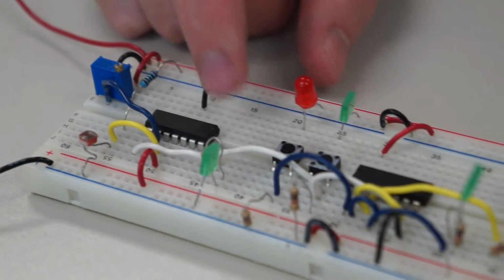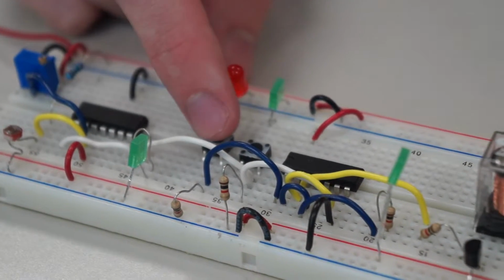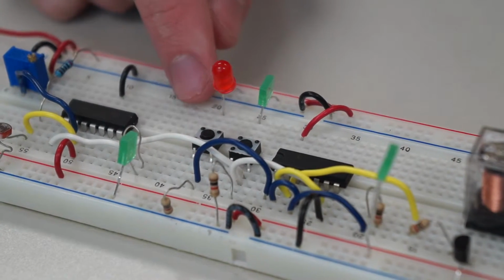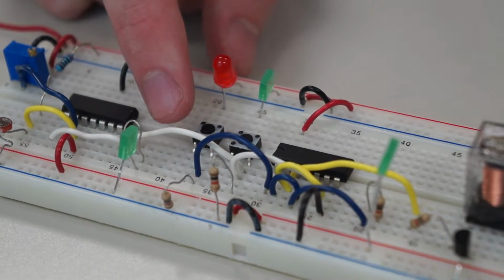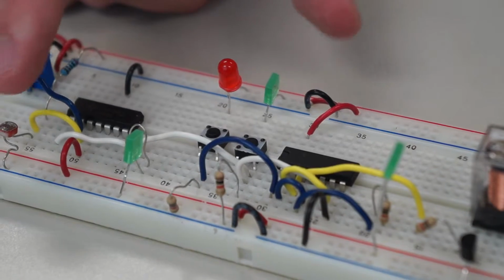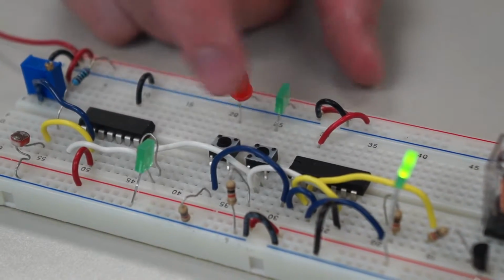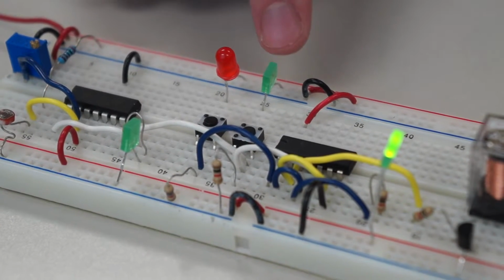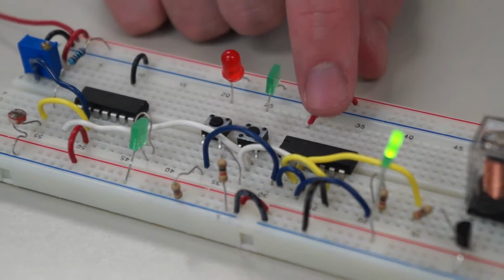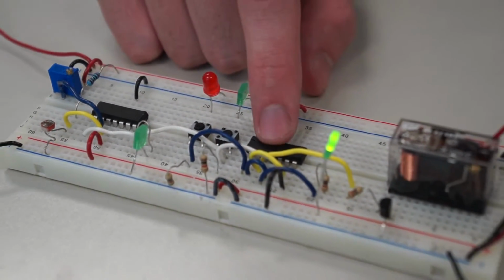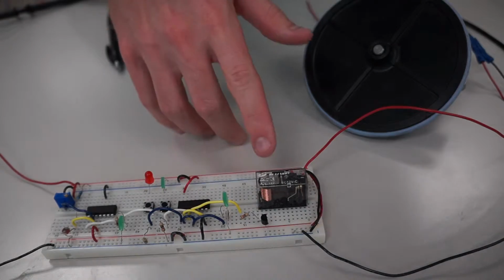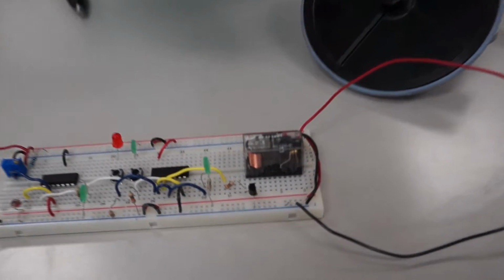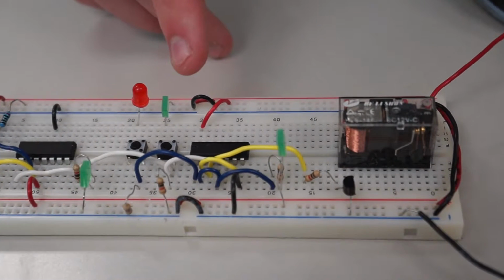And if the variable resistor is higher, it will send it to this switch right here, which is the reset part of the second subsystem. And if the LDR is higher, it will send it to this switch, which is an automatic switch, and it's the set part of this. Now this goes to an RS flip-flop right here. Subsystem 3 is controlled by subsystem 1 and subsystem 2's outputs.